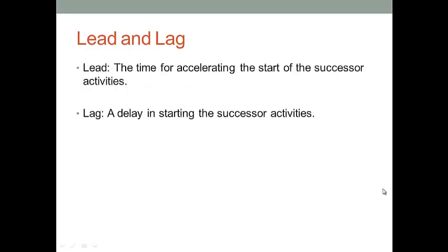Another important concept is the lead and the lag. A lead refers to the time saved when we complete the first activity early. Let's say we plan to finish the first activity in 7 days, but we actually used 5 days to complete the first activity. Then we will have a 2-day lead after the first activity.